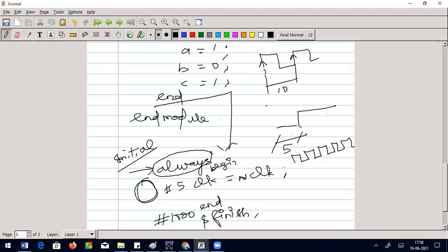If I am giving an input signal every 5 units of time, what would happen? Definitely it will miss the signal or input between two subsequent inputs. Why is it missing? Because the clock can capture only the signal after every 10 units of time, but you are changing the input every 5 units of time.